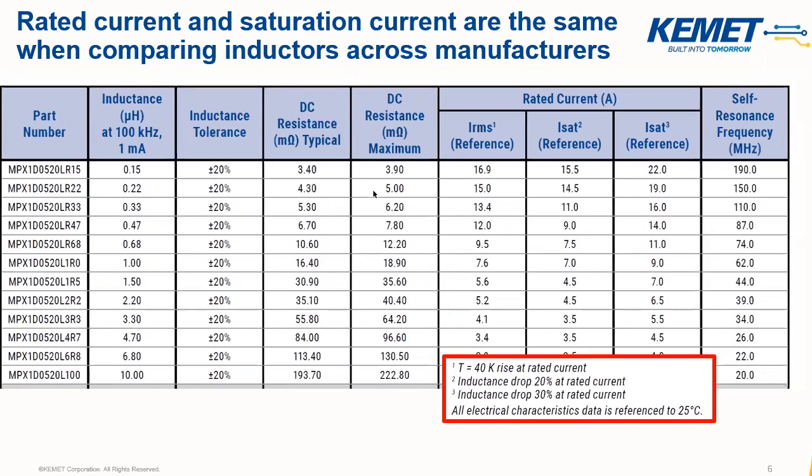Yeah, so it seems like you have to be very careful looking at when manufacturers define their points of rated current and saturation current. As you're designing that in, you have to say, well, under what conditions is that number defined to be?